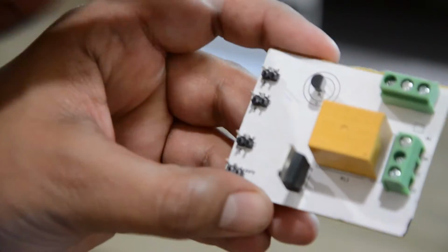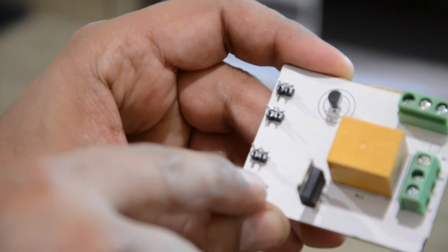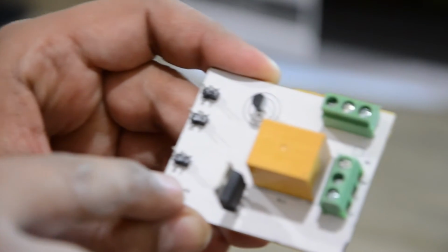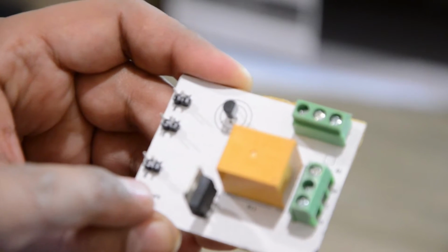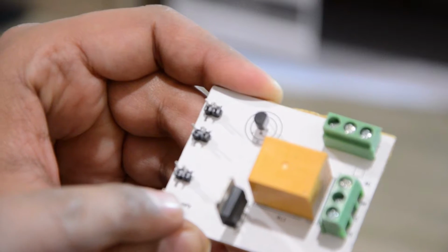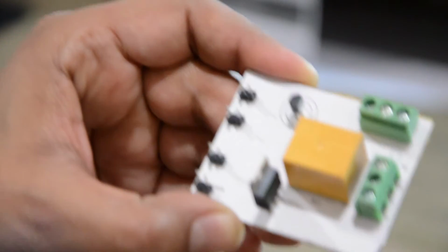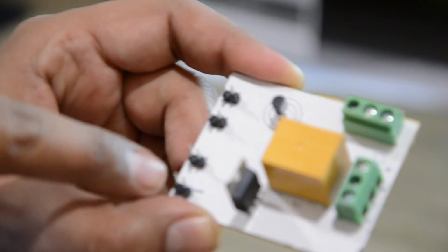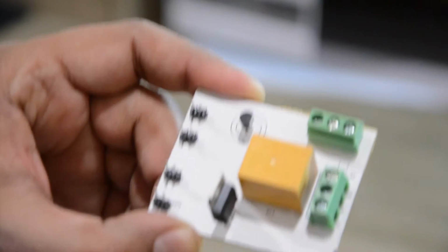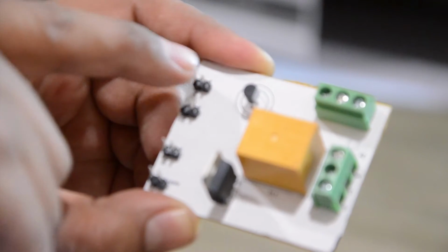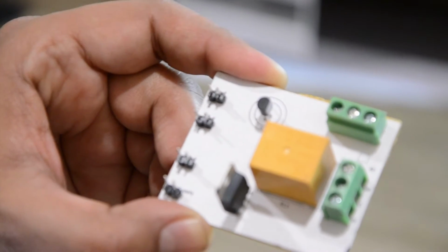Now over here is a 12 volt supply input, which we would be feeding in through an adapter, and in case we have a strip adapter like the one that we use for the LED strip lights, we can connect it using the AC pins over here and give the 12 volt input over here. The left one is the ground pin and the right one is the plus 12. This is the digital input for us to work with.